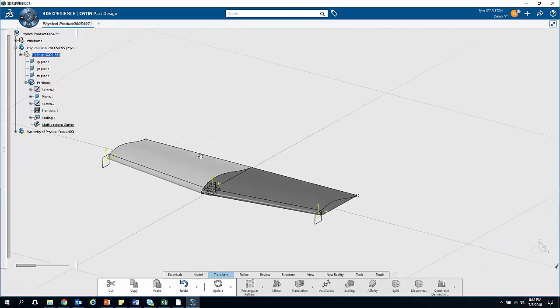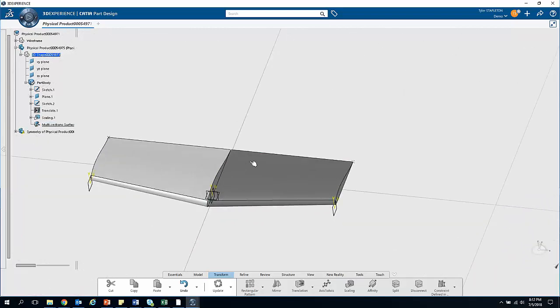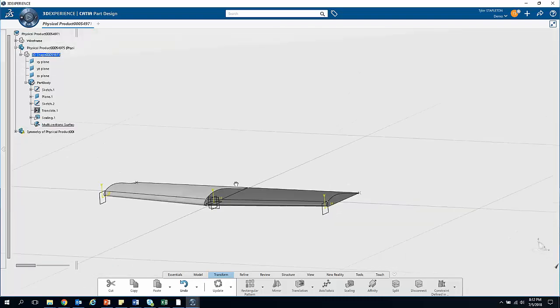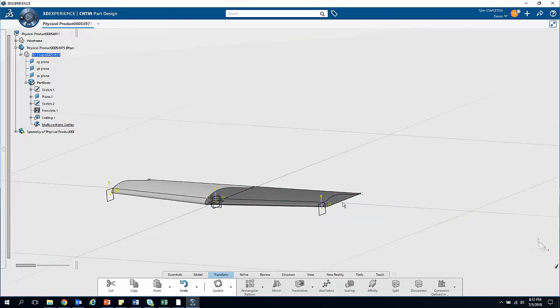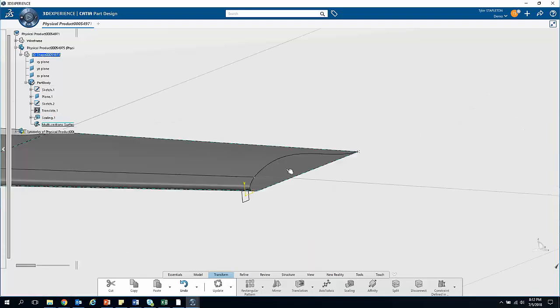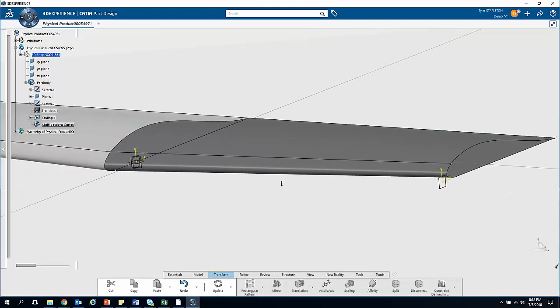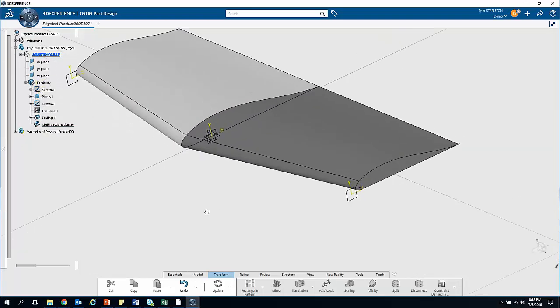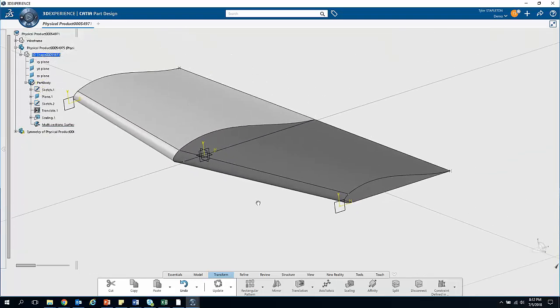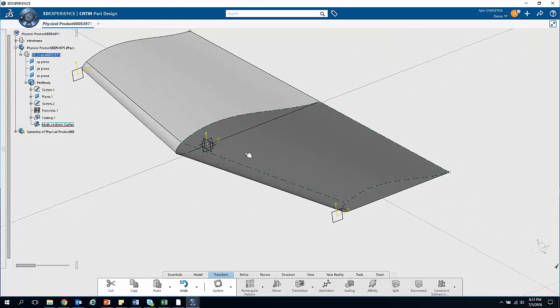Now you can do a lot of different things with this. I could create a sketch here in part design, and I could pad some geometry and have it come up to the surface so that it meets that curve exactly. I can do that on the inside as well as the outside. So if I want to create ribs, I could use the surface to define the outside geometry of the ribs within my airfoil. But what I want to create here is actually just the outer shell. So this would be the carbon fiber, the fiberglass, whatever shell that we're putting on here.